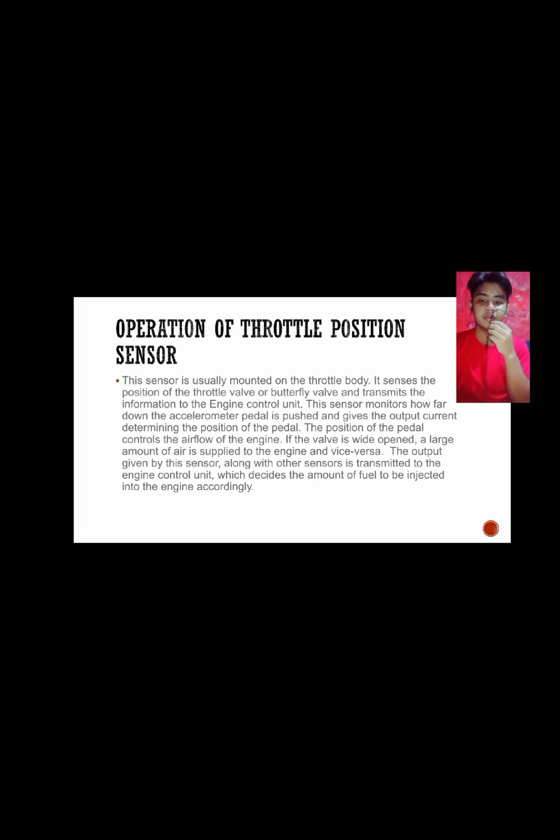Ang next naman natin pag-uusapan ay ang kanyang operation. This sensor is usually mounted on the throttle body. It senses the position of the throttle bar or butterfly valve and transmits the information to the engine control unit. This sensor monitors how far down the accelerator pedal is pushed and gives the output current determining the position of the pedal.